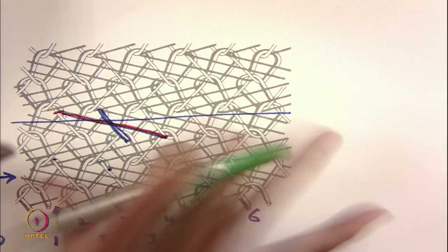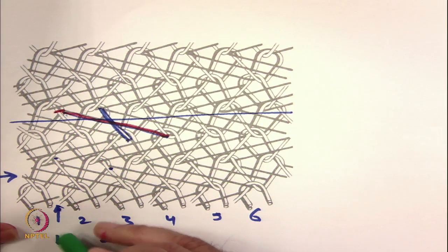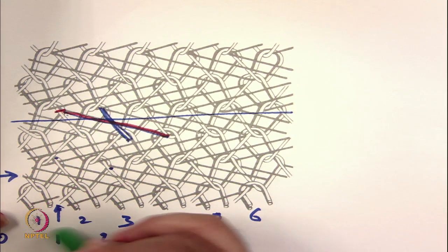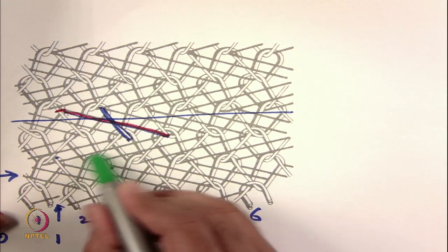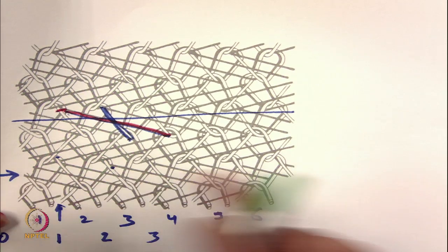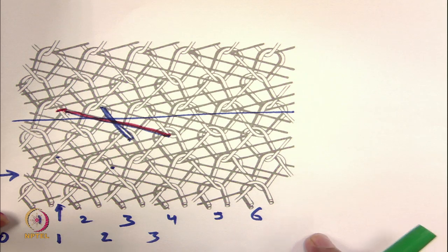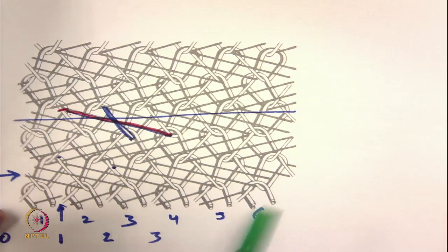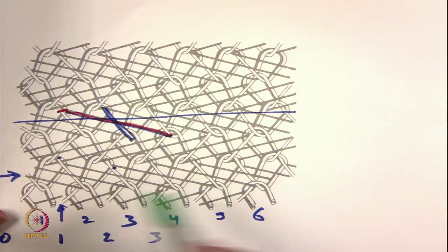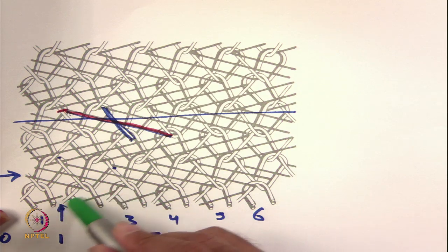So, this is the lapping diagram for one guide which is carrying the white yarn in this particular fabric. Now, let us follow the black yarn. As you have chosen guide number 1 position and from there followed the white yarn, similarly for the black yarn you can start from any position 0, 1, 2, 3, 4, 5, and follow in the same way we followed the white yarn. So, let us suppose we are following from the second position. If you see this particular yarn,